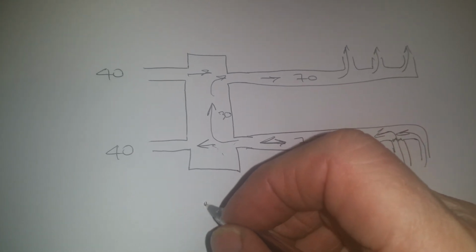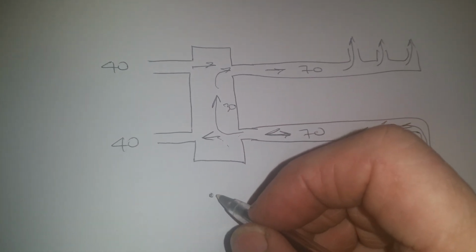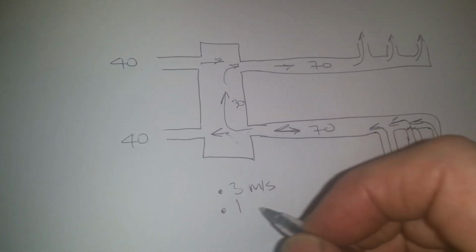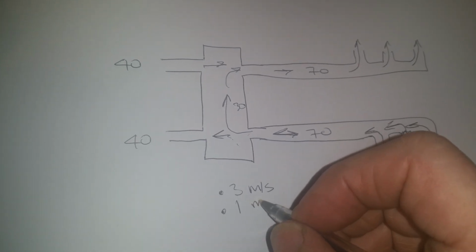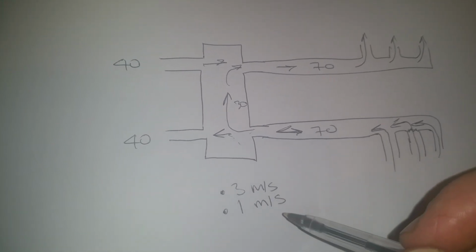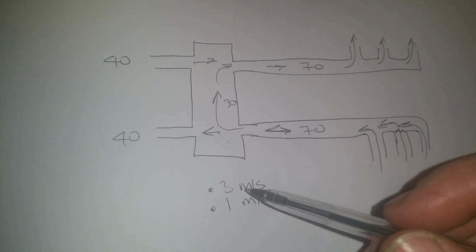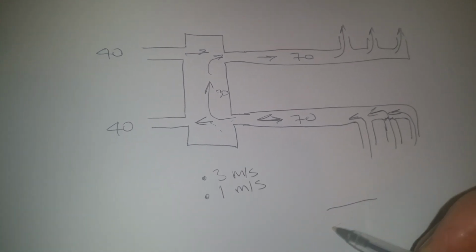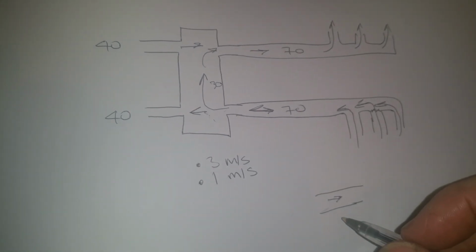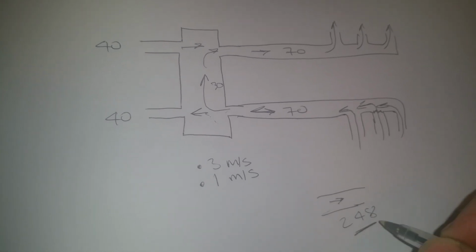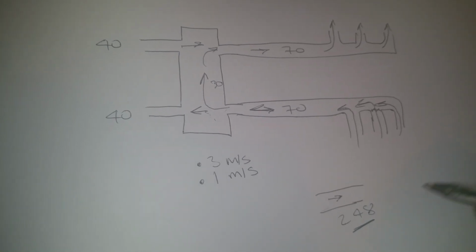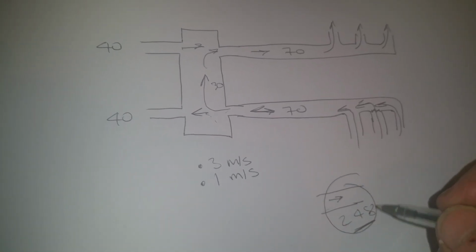And the various different sources give different flow rates. I use less than 0.3 meters per second, and I've seen it as low as some requiring it to be lower than 0.1 meter per second to get the low head losses. So if you look in the CIBSE design book, you'll see that for any given tube, the lower the flow rate, the lower the resistance, and this also goes on to the pump 2-4-8 relationship, where if you double the flow, you get 4 times the resistance to flow, and it requires 8 times the power. Try not to go off onto too many tangents.